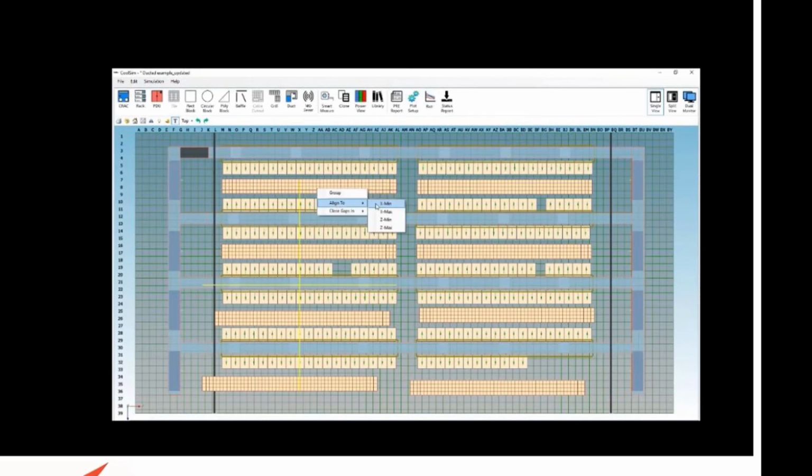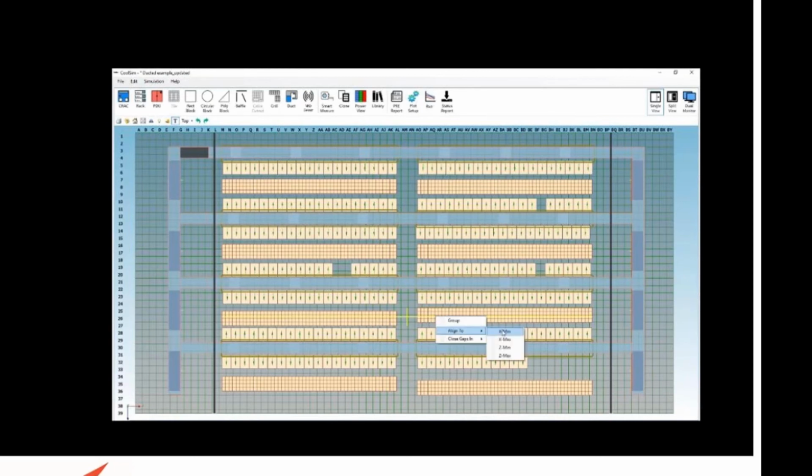I do want to line these up, so I select them all, put my cursor over the one that I want to hold constant, line them up in the X direction, do the same thing over here, Control C. I'm just selecting with my left mouse button, put my cursor up on the one to hold constant, align to X min, boom, they're all lined up. Now, don't forget, you've got to supply a way for the air to get down to the intake on those crack units. Oh, I guess I lined a few up in the other axes as well.